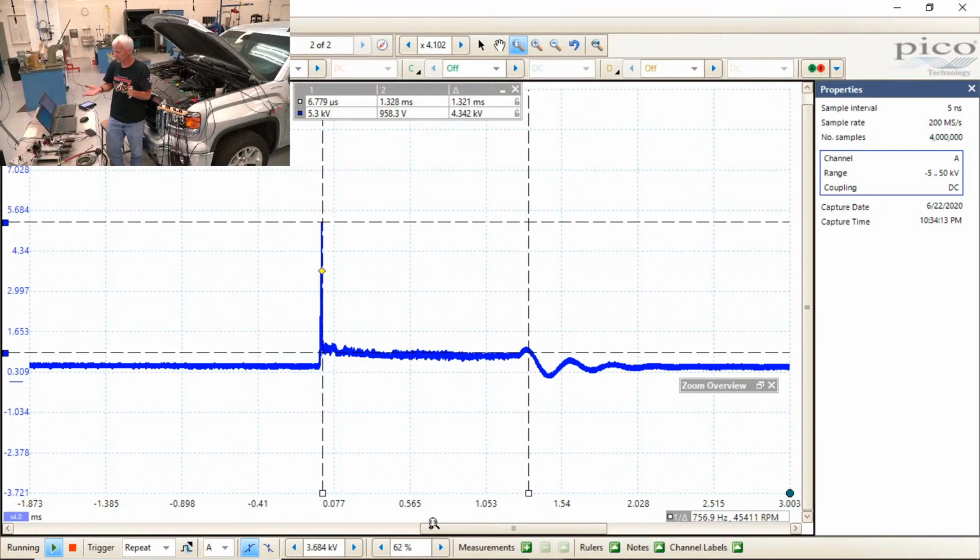So now, this little mock-up here doesn't always 100% transfer over to real life. On this vehicle here, if I go to hook it up, because I do have spark plug wires, these are coil-over-plug situations, so I can actually hook up to a spark plug wire. They got these little baby spark plug wires. And if I didn't have a spark plug wire, if I was a coil on plug, they make these wands that you can lay on the coil. Sometimes they work, sometimes they don't.